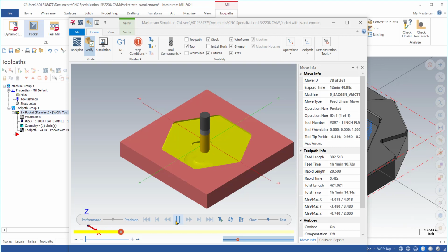All right. So you see, because of the way the shape is, here even 90% is working out fine, so we don't get any issue. It will be more of an issue when you have irregular shaped pockets. So the best way is to check it and verify, and if you see within those step overs that it's leaving some scallops, that means we need to make changes. But in this case, 90% is working out fine.